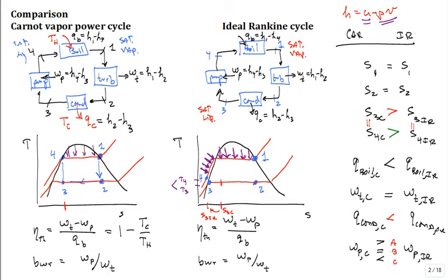It doesn't cost us much mechanical energy to boost the pressure of an incompressible substance. Pumps are cheap to run. Air compressors, very expensive. Steam compressed as a two-phase mixture is going to be more expensive than a liquid, so more expensive per kilogram of substance that's undergoing the pressure boost.